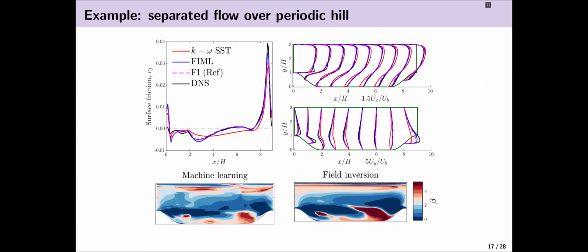We haven't really looked into trying to make it smooth. Part of the reason that it's not smooth is because when we're doing field inversion, the beta field is frozen during the CFD simulation, and once it converges, that makes it even smoother during the optimization. It's fixed, but when we use the neural network to do the CFD simulation, the beta field is predicted for every iteration.